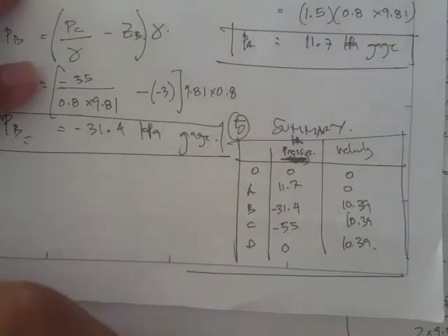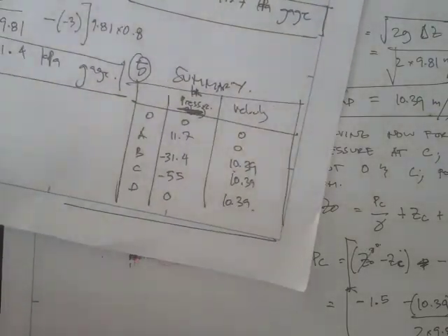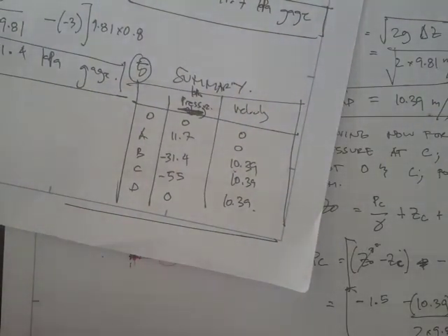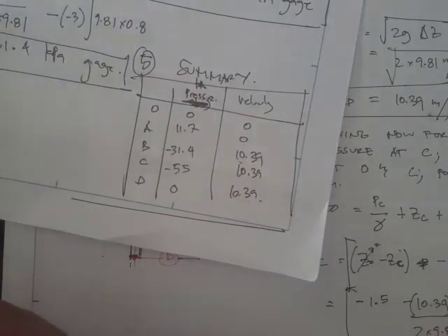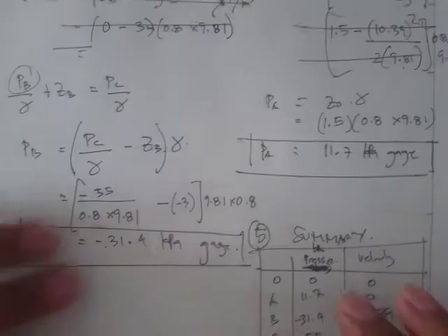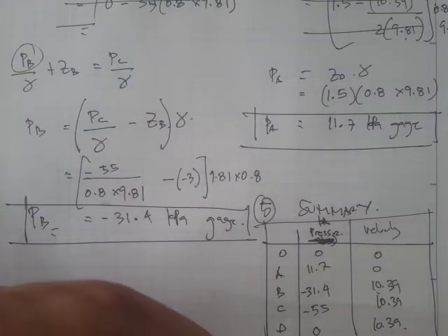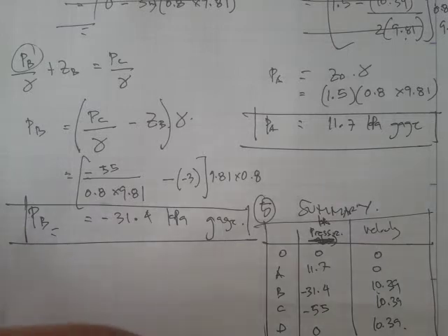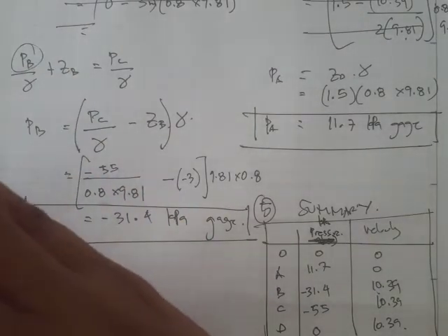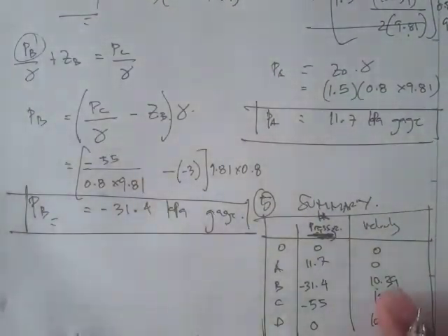Just a couple of notes before we move on to our next topic. Be careful when you apply Bernoulli's equation. Make sure you can assume that the frictional effects of the viscous force can be neglected, or in other words, that those frictional effects are way smaller compared to the effects of pressure, elevation, and things like that. All right.